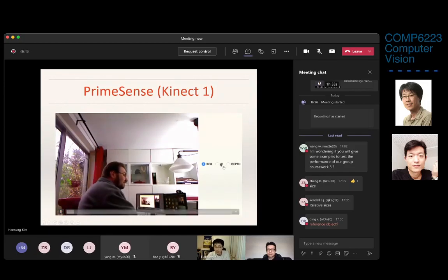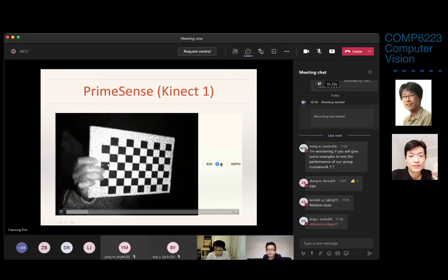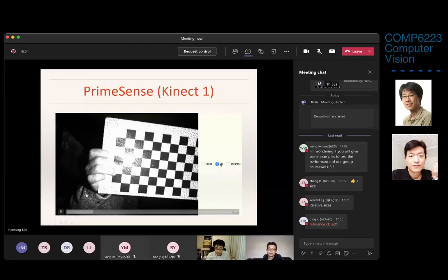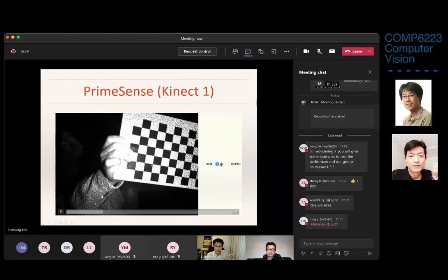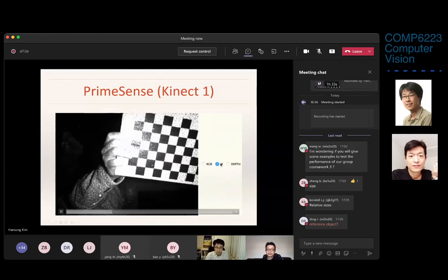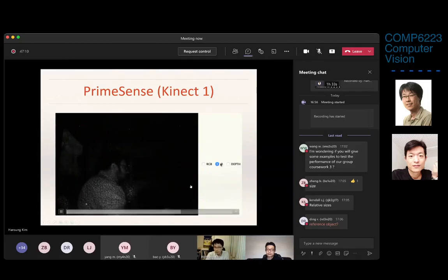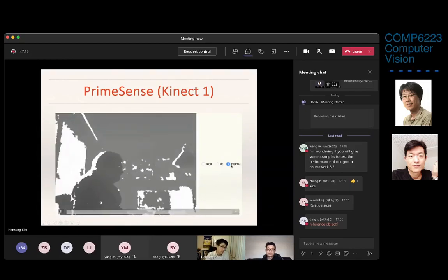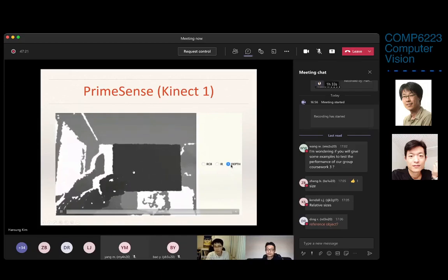If you switch to the IR camera, now we just change the IR pattern to visible light. Now you can see some distinct dots, right? And they are a bit distorted according to the depth and the pattern of the surface. You can see the kind of pattern I showed you projected on the surface. So the IR camera can detect this pattern, and from the distortion of this pattern and pattern matching, we get some kind of depth. Now it will show the depth estimation from the IR pattern. Now we get this depth. You can see the darker, the closer; the brighter, the farther. Right? You can see the clear depth.